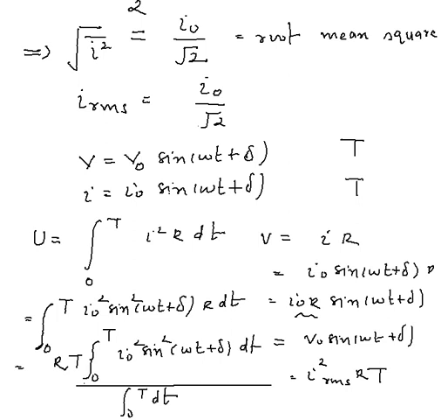It is not the mean current. Mean current is simply out of question. Resistor is going to eat energy every instant and average current is 0. So average current is simply out. It is not I naught, it is IRMS. So IRMS has great significance for us. And IRMS is given by I naught by under root 2. So with this we stop now and we continue in the next class.